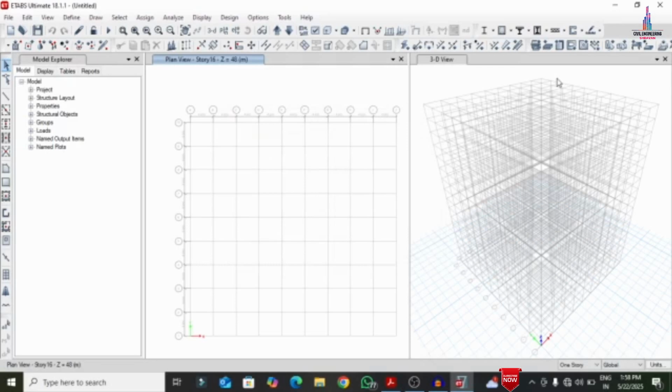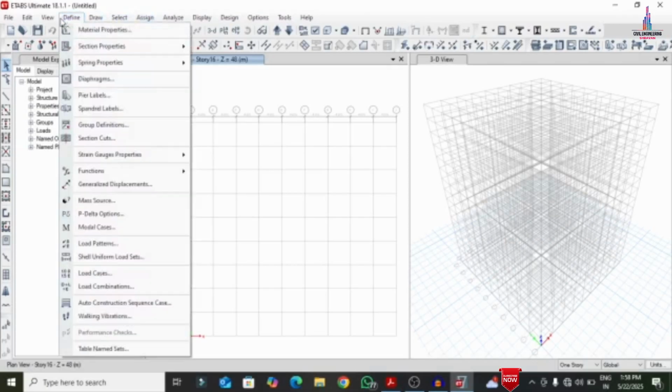Now we have to define the shear wall thickness for the tube-in-tube structure. As per the considerations of the IS code provision standard system, the maximum shear wall thickness is assumed as 500 mm and the minimum size will be 100 mm. You can consider any thickness between 100 mm and 500 mm. Here I am considering 230 mm as the thickness of the shear wall.